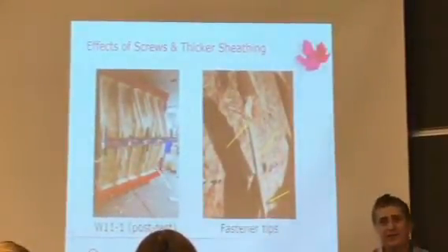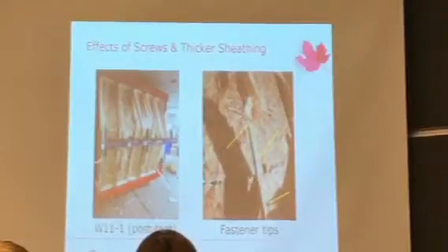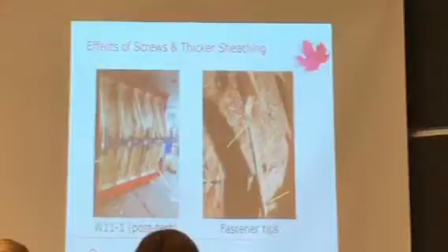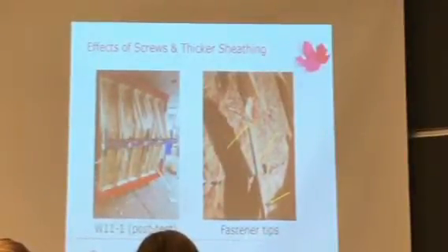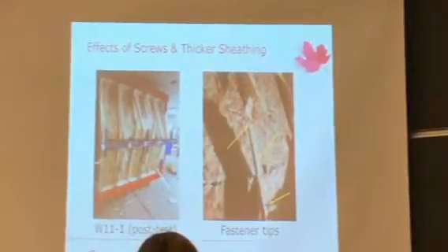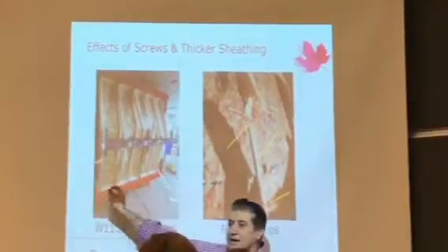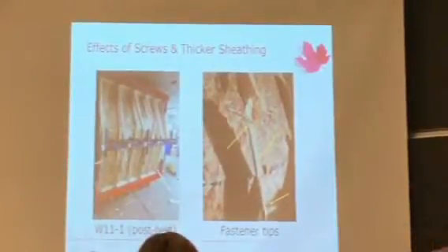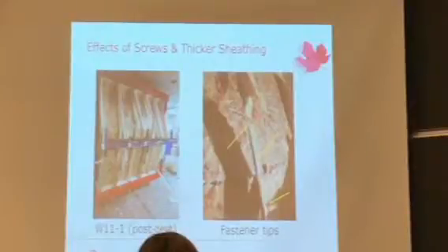Logical would be that I would go back to the student and say, use longer screws. The student said, heck with you, I'm leaving. Right? He was done. It's like, my master's finished, I'm gone. So we didn't do it. But essentially what we showed is that if you are able to grab onto the stud, and if you're able to have a thick enough sheathing, you can actually maintain the wall there without it just flying away and hitting people on the head.